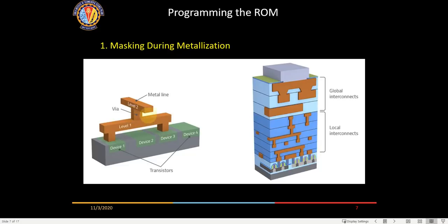To make it compact, since a single metal layer would waste a lot of silicon area with millions of connections, you have multiple metal layers with insulation between them. You can run different metals one over the other, and wherever you need to connect two metals, you make a small hole, a via.